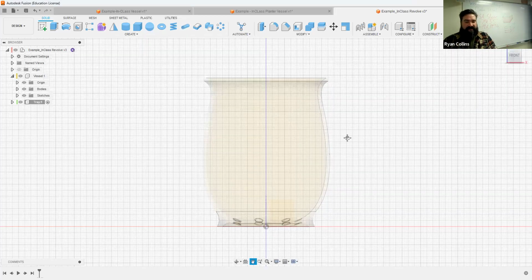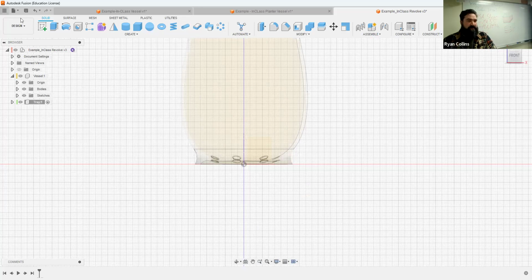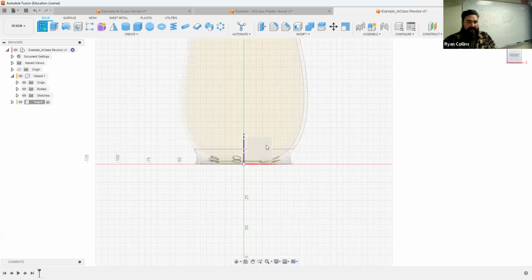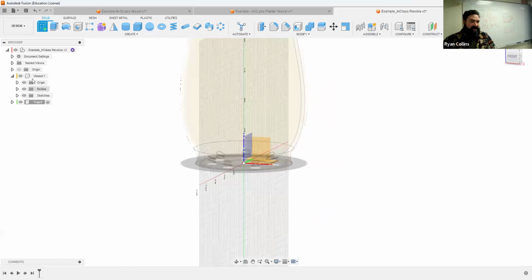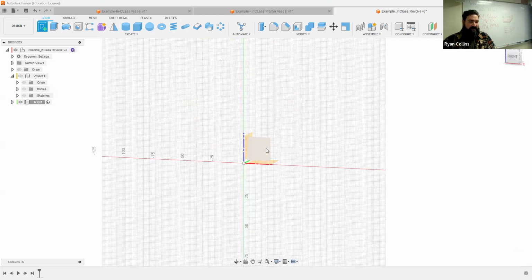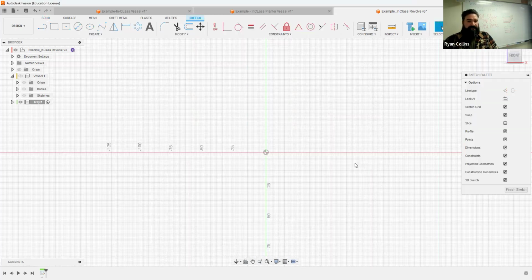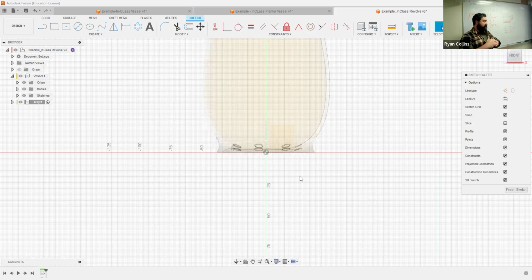I need to create a sketch to create the revolve for my tray. Same deal, selecting the XZ axis. Sometimes even though it's not active, having the bodies of that component visible makes it difficult to select the plane. So that's why I say you want to toggle the visibility on that. So there we go. But I like having it visible so I know where it is. These do not have to touch to print. Most certainly you don't want them touching, but they don't have to touch when you're modeling them. It might help make more sense, but they don't technically have to.